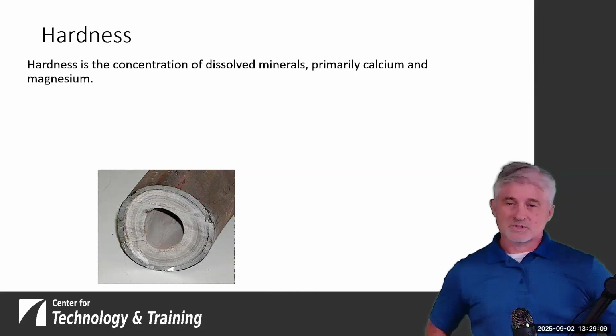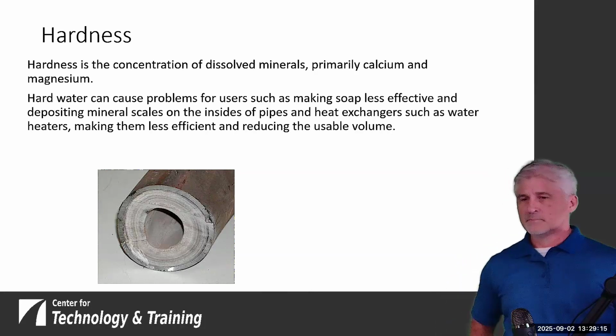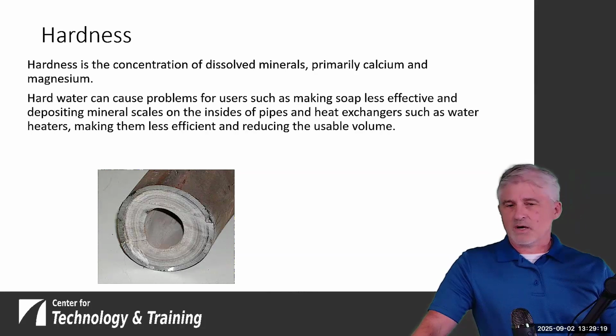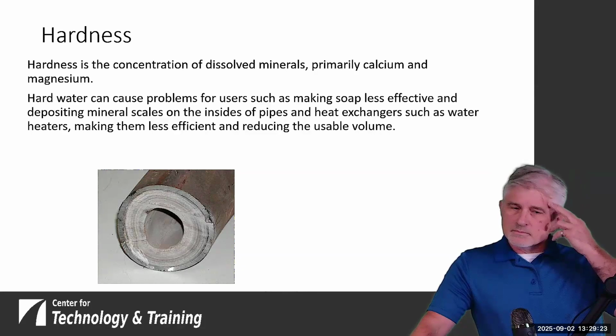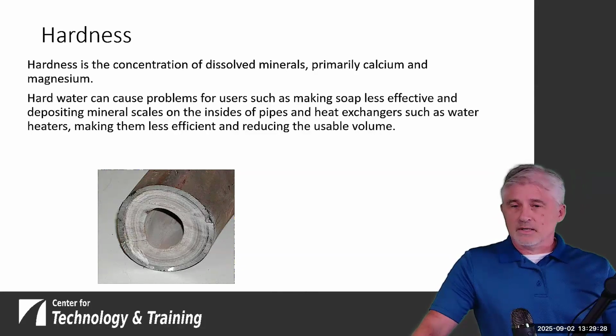Typically, source water systems don't start with high hardness, but it's important to have some hardness when it comes to preventing the leaching of lead and copper. Hard water will cause scale to build up on pipes, and that's important when it comes to preventing the leaching of lead and copper from pipes.